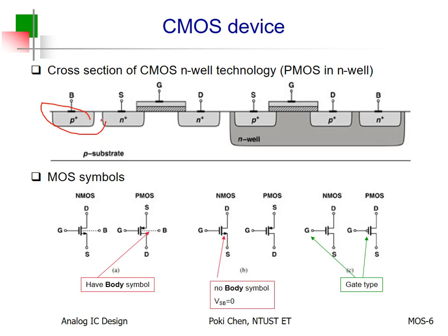Who can help you? No, nobody can help you, because for here and there, the parasitic diode can be erased, canceled by gate voltage. But we don't have another gate voltage to help you, right? So don't be silly. Here, you cannot dope it as N plus. Only P plus can help you. So it means the terminal here will be connected to P plus and to P minus all the way to your body.